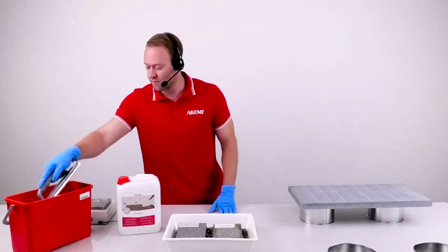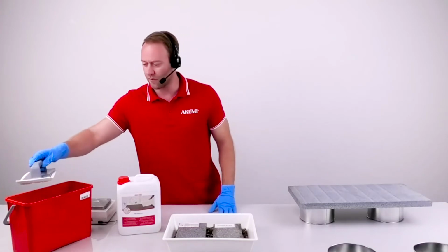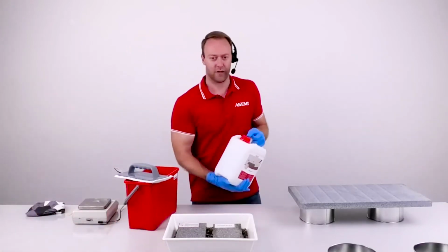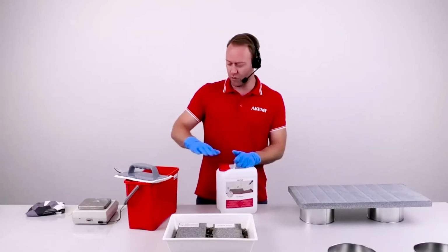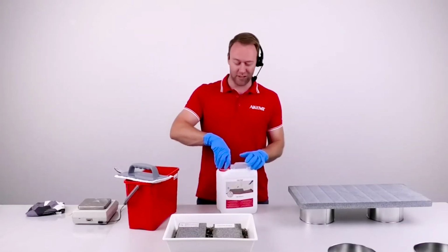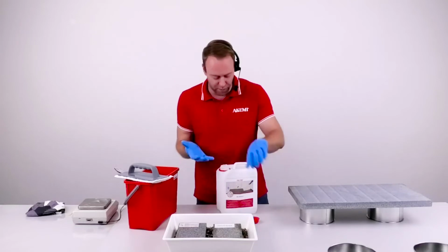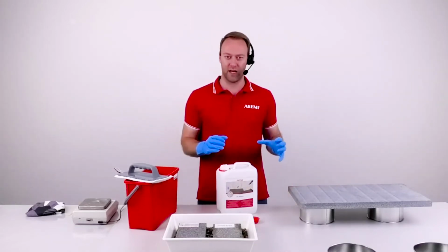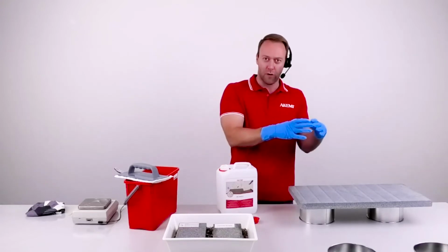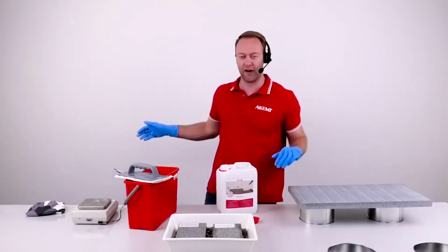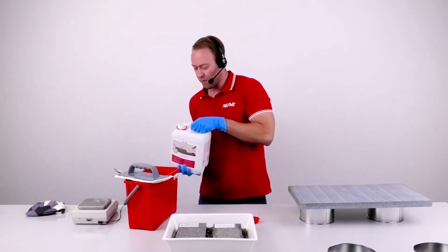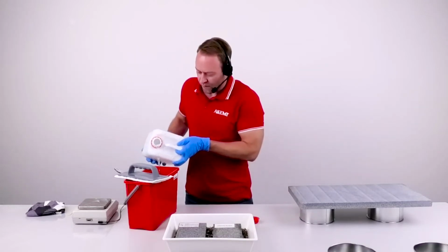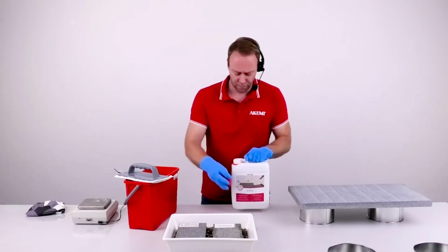As always, don't just put the product on the stone. Always use a canister, because I always come to construction sites and see people pouring it and then spreading it. This will not make a good performance. You have a lot of concentration of sealer on one area, and then in some other areas you will have very little. So always use a canister and a device, a tool to apply it.